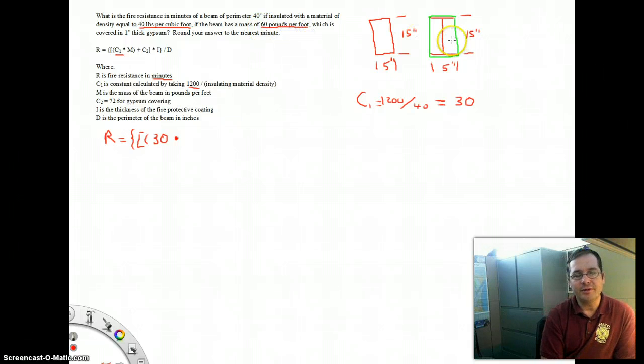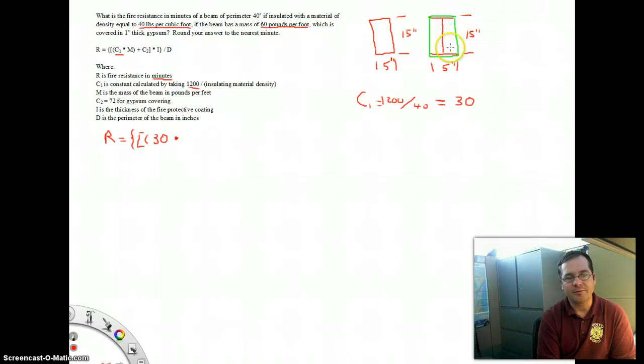So the story with beams like this is that you might imagine that they could make this beam with webs and flanges, webs and a flange of any thickness really that you'd want. And so to describe how thick the metal is, typically this beam would be sold as a 15-inch by 5-inch wide flange beam at a weight of 60 pounds per foot.